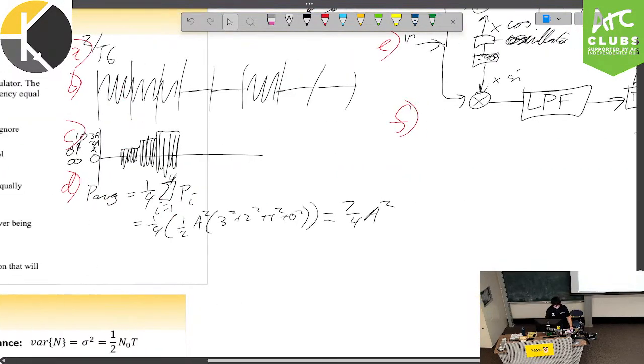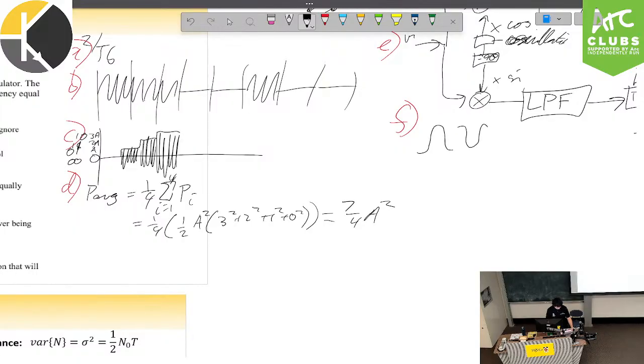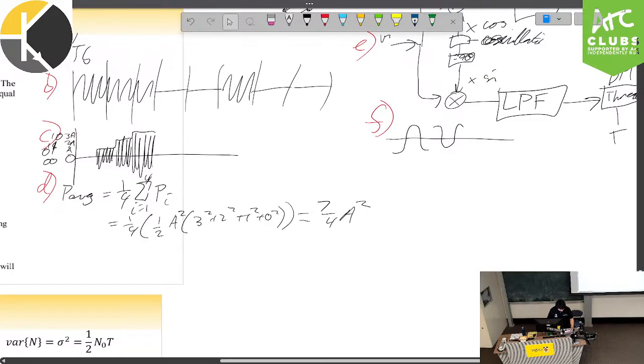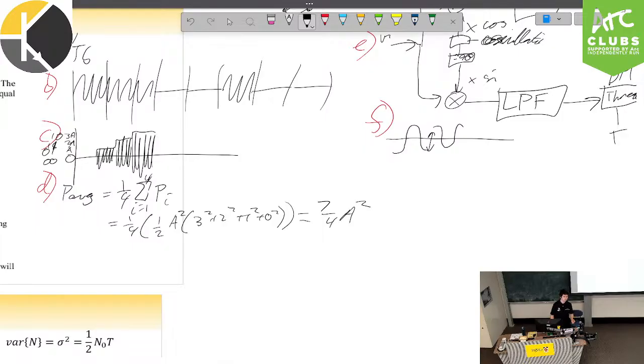So binary phase shift keying, just note that they go from here to there. That's how it works. And so you have a bump difference of 2 times the amplitude between different signals. Okay, so it's a very big difference. And to overcome that, your noise signal very much has to bounce more than a whole amplitude of your signal, rather than typically half the amplitude of your signal.